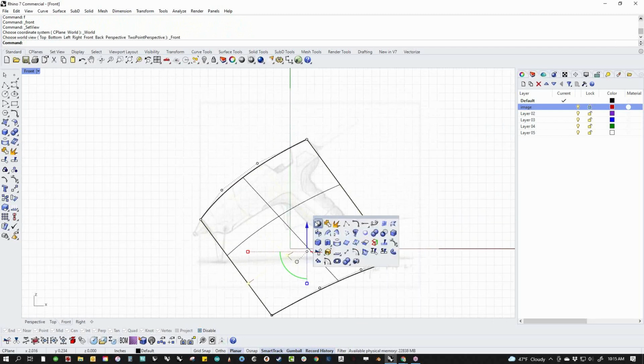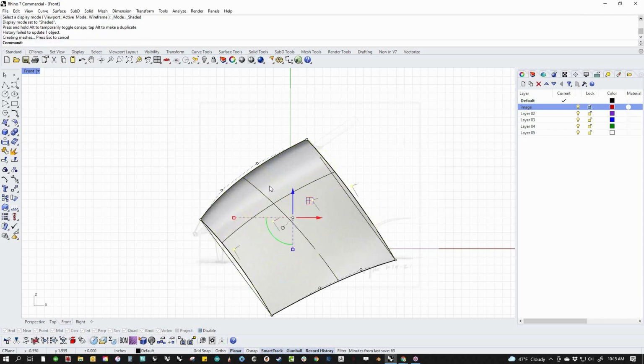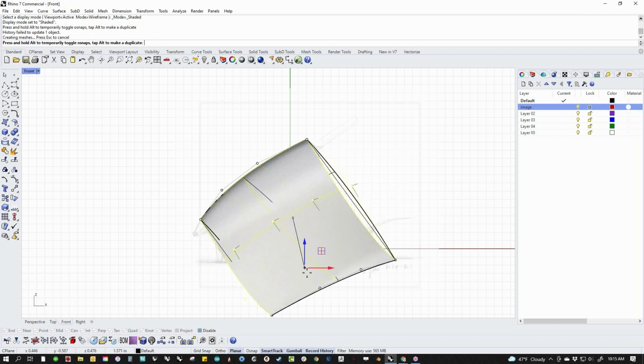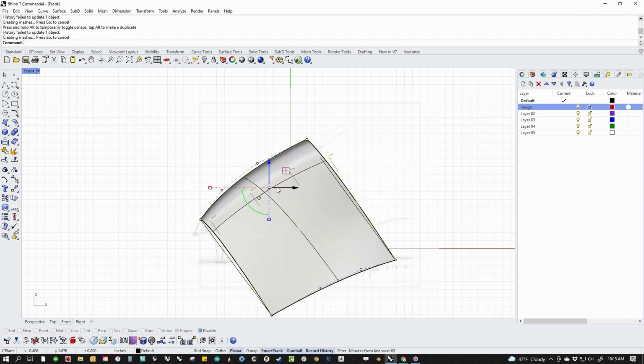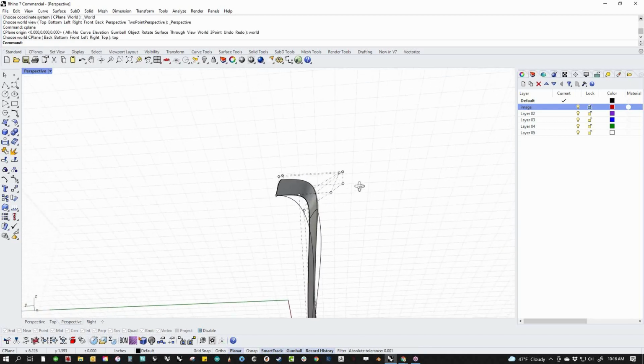And I'm going to just go to shaded mode, and I'm going to use my C-plane waffle and see how that highlight's moving. You see this right here? See this band of highlight right here? As I move that, look what happens. I can move that up or down, and on this particular form, it probably is pretty high. So I'm actually going to tuck this way up there. I'm going to pull it back a little bit like that. So my highlight is tracking in the right place now, right? See that? How high that is?